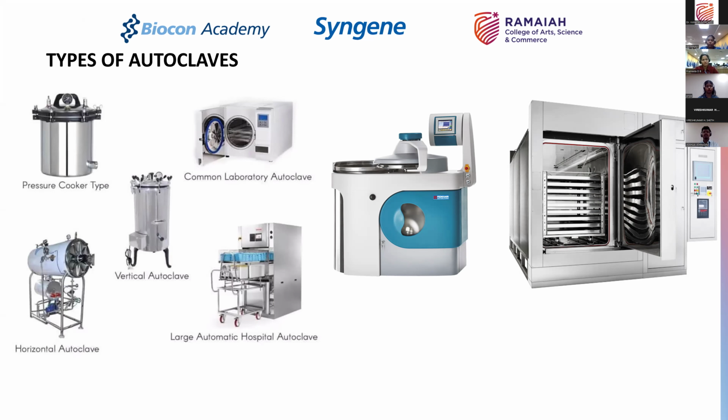So the pure steam generators are a separate, independent equipment, which are kept in a central location, from where there is a steam line which is run to all the equipments which use steam. Connection is given to the autoclave, and generally at the autoclave junction you will have a pressure regulation valve.